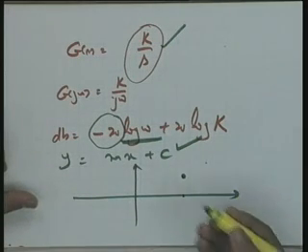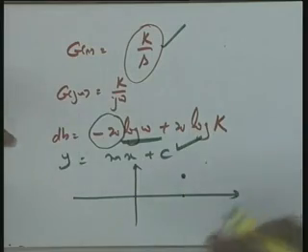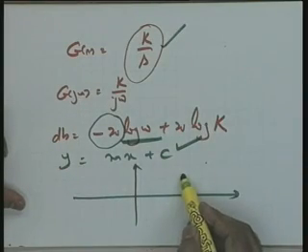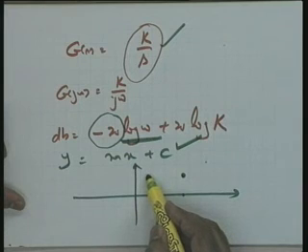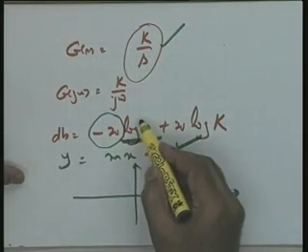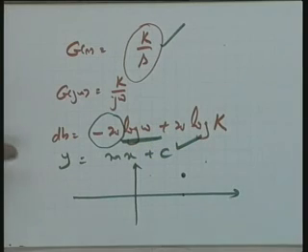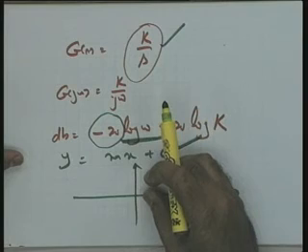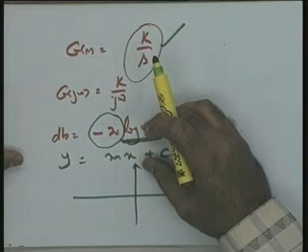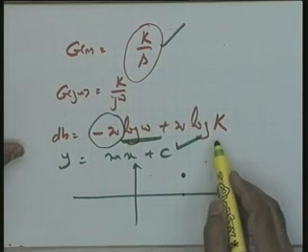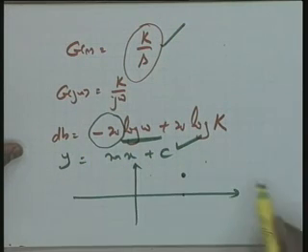So I will suggest that you go this way, it depends how comfortable you are with drawing a parallel line, fine, otherwise you take a point. Take a point correspondingly at the location with the same dB one decade below and make it 20 dBs up, and let it pass through this point. You can take a corresponding point with the same magnitude on the other side and then take it 20 dBs up. So in that case, from this particular point, if you make a line, a minus 20 dBs per decade line could be drawn.